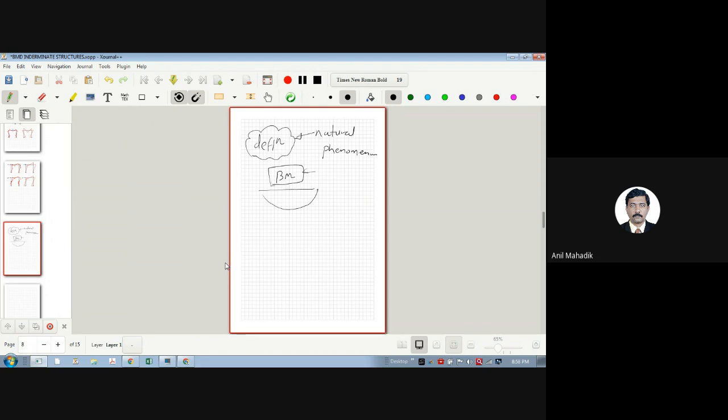They have created the frames using that spring arrangement and steel balls with fixed supports. The steel ball acts as a hinge support, and if you provide a 90-degree steel angle there, then it becomes a fixed support. And then how the behavior changes, all those things are given.